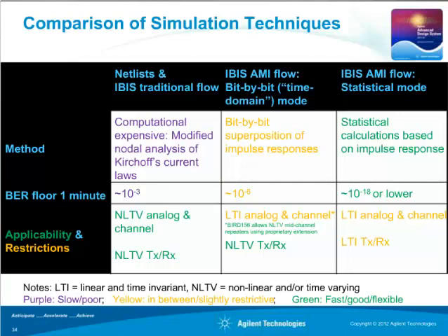The constraint with statistical mode is simply this, that yes, the channel needs to be linear time invariant, but so do the transmit and receive. Transmitters, that's usually okay. On the receive side, if you had some kind of nonlinear functionality like a DFE, then you would need to think about that very carefully, decide whether or not you could have a linearized model of that and still get useful information. And in many cases, you can. So that is the trade-off, if you like, from the fully general purpose but slow SPICE environment to the extremely fast statistical environment that's available inside the channel simulator.